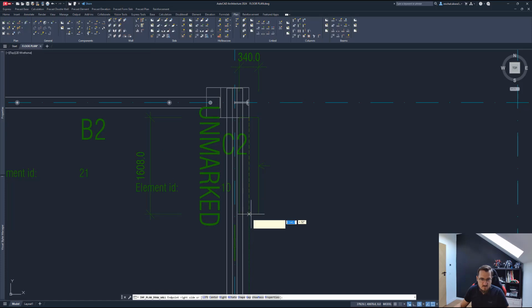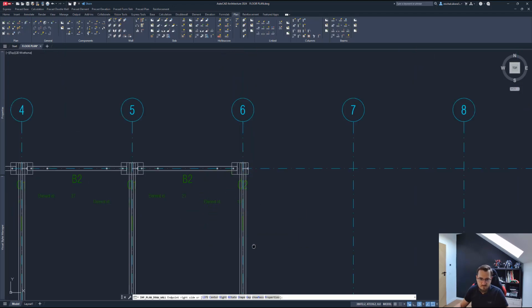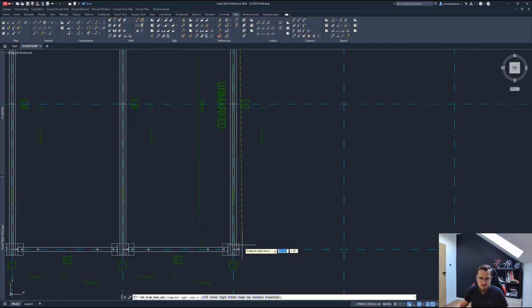I don't have to change anything since I'm going this direction, but what I want to change is the alignment of the wall. So I will just press LE on the keyboard as per the tooltips on the bottom, and I'm good. I place the wall on the left side of the placement line. So I'm just going to click.